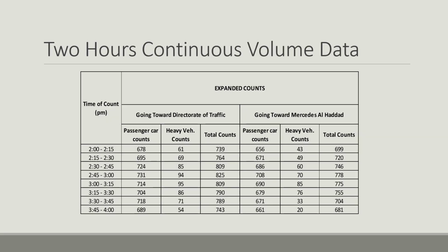The table shown here shows the counts converted to a 15-minute counting period, and that's done by multiplying the value from the previous table by 15 and then dividing by 12. The same procedure is repeated for all the values to convert them to the 15-minute counting period.